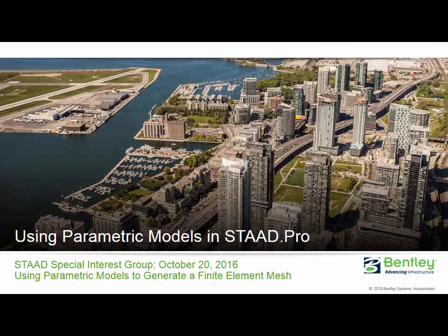Now let's go ahead and introduce what the topic of parametric models are. In STAAD Pro you do have several different options for generating a finite element mesh. We have a couple of traditional finite element mesh tools such as your Generate Surface Meshing tool or your Modeling Plates tools. Those of course are perfectly acceptable to use, but what I want to show you today is some of the advantages of using a parametric model in order to generate a finite element mesh instead of those traditional options.